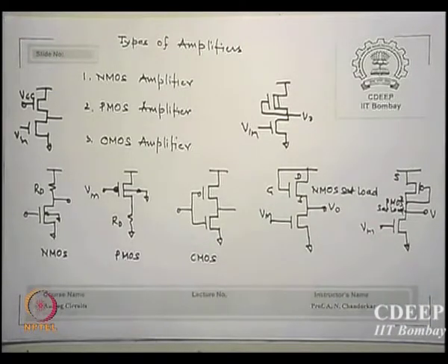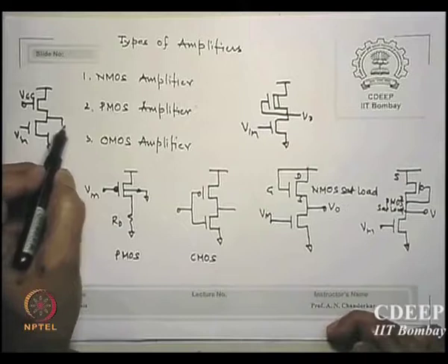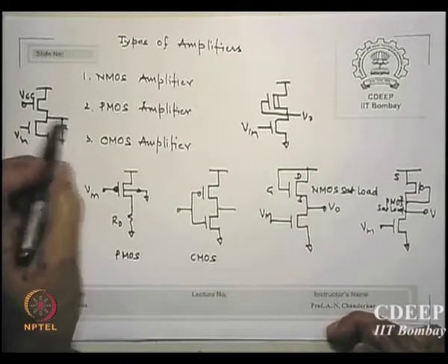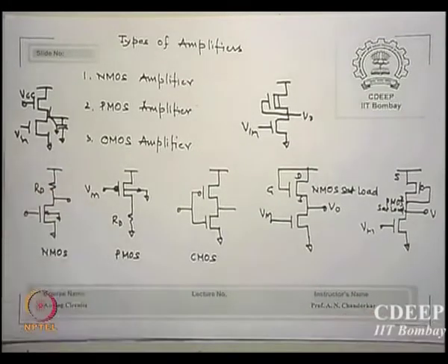Increase. So this is what digital people do: if you have a capacitive load here and this is to be charged, what if R is larger, what is the time constant? Larger. So switching frequency will be lower. If R is lower, switching frequencies are higher, and so is the bandwidth connected to it. Is that correct? So somewhere power and frequency are getting related.